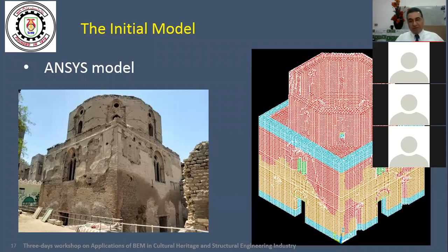I believe so. First of all, I think from a model point of view, the model would be much larger, because you'll also have to model the mortar in between. So the number of elements will be huge. And as I said, if we're talking about a linear problem, which is just getting the mode shape, I don't believe it will make that much difference.